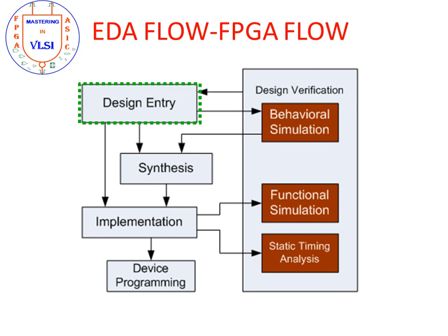And in the verification phase, there are two very important things. One is functionality verification and another one is timing analysis. Functionality verification will verify whether the intended functionality will be completed or not. Whereas in the static timing analysis, we check whether the intended functionality will be completed in the specific time or not. Here we will do one example and then go to the remaining.